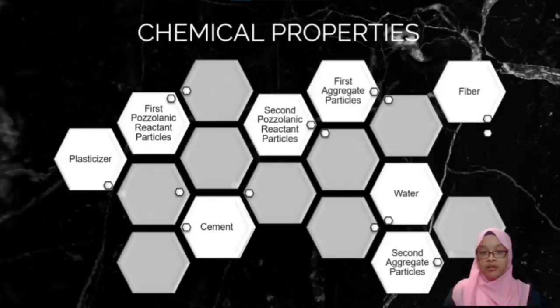In this case, the first pozzolanic reactant particle and the second pozzolanic reactant are impalpable powder to be involved in the pozzolanic reaction and make the cement matrix dense by the microfiller effect and cement deflocculation effect of fine particles. It should be noted that the pozzolanic reaction is a reaction in which the pozzolanic substance reacts with the alkaline substance produced by the cement hydration reaction to gradually form a hardening body, which contributes to long-term and